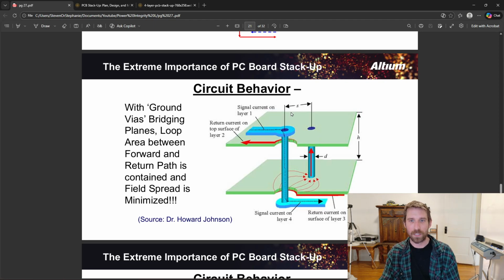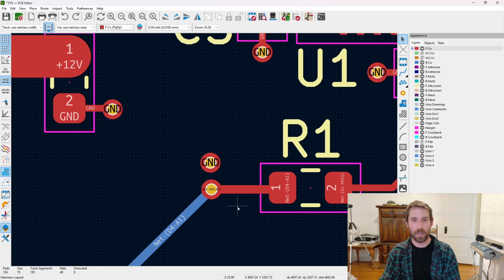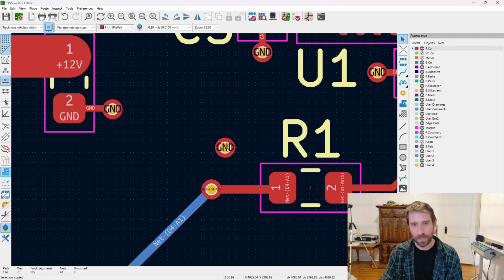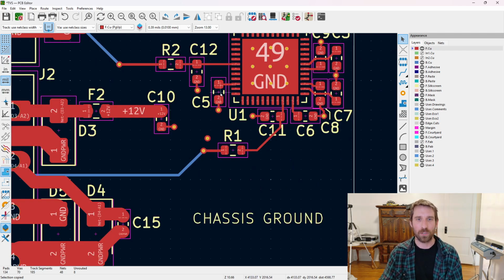So you want this spacing small, of course. Then height's already reduced because we're going to a 4-layer board. So like this, and it's so easy to do. What I do is I usually do my ground planes first in a design. That way when I need a signal via, I can just go pop right there, done. So I don't obsess over this distance. Dude, if I click and I'm just like right there, whatever. Because I know that anything I do here will be so much closer than here.